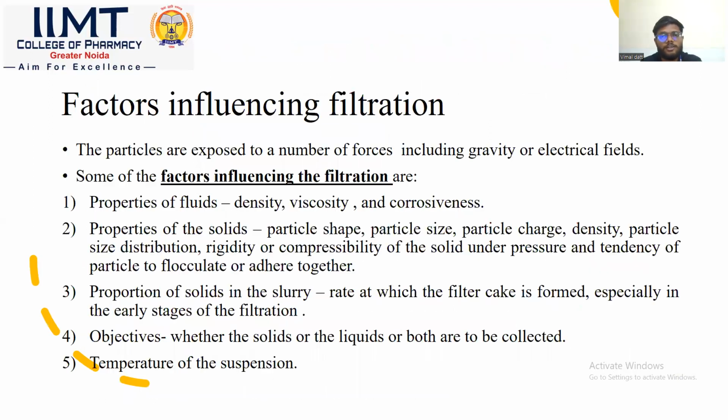Factors influencing filtration. The particles are exposed to a number of forces including gravity or electrical fields. Some of the factors influencing the filtration are properties of fluid: density, viscosity, and corrosiveness. Second is properties of the solid particles: shape, particle size, particle charge, density, particle size distribution, rigidity or compressibility of the solid under pressure, and tendency of particles to flocculate or adhere together.